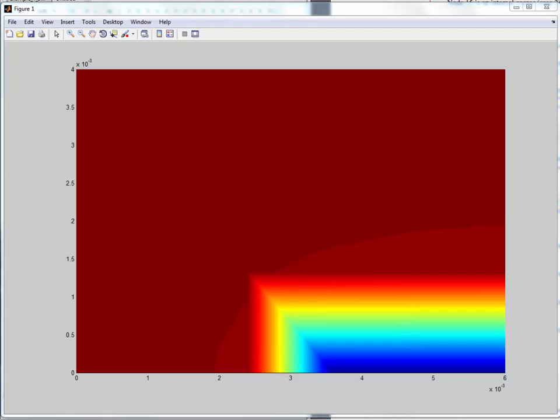Notice that as we predicted, the higher temperature is going to be closer to the surfaces that are exposed to the hot gases, and the lower temperatures are going to be closer to the air in the channel. However, the temperature distribution is actually around 1500 Kelvin, so that's why there is not a high gradient within the distribution that we see in this plot.